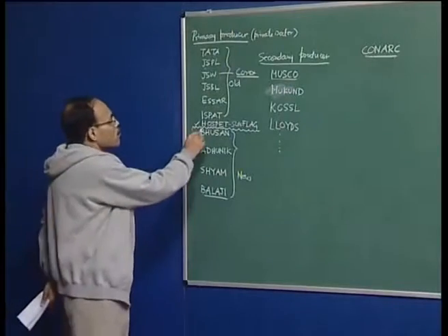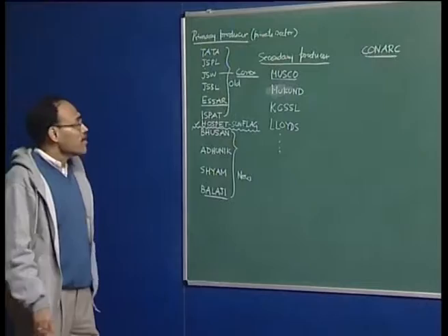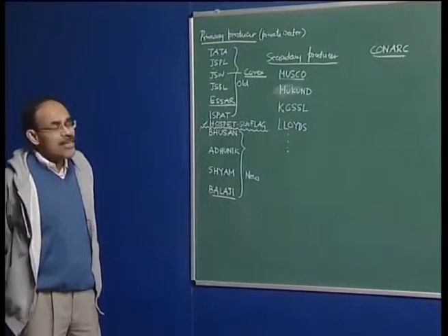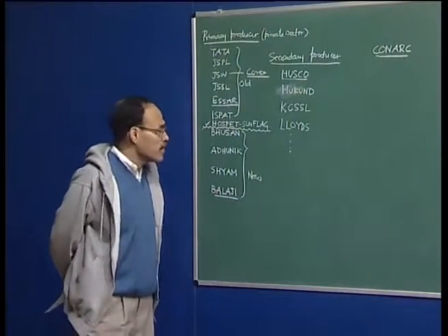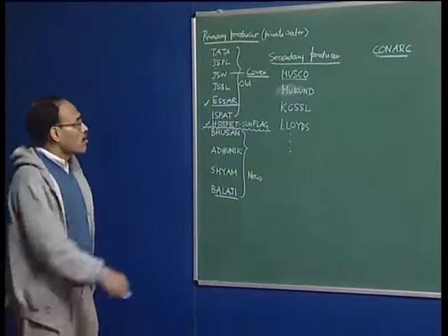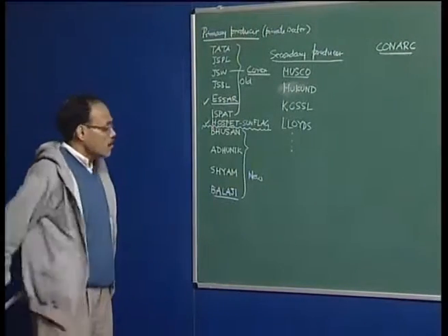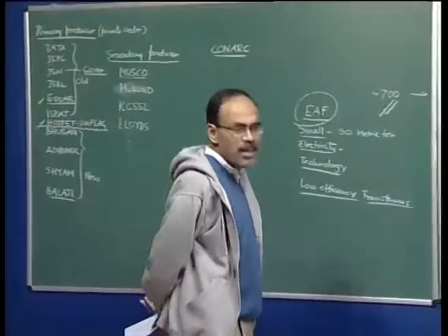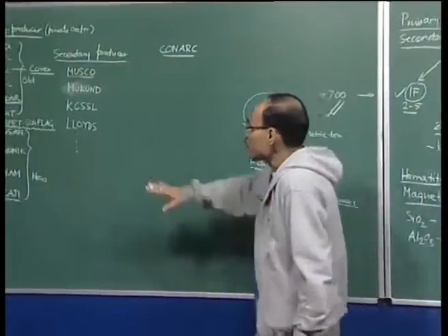So if you go to SR Steel, you find they have a huge electric furnace facility. By the way, SR has the biggest DRI plant, 3.6 million tons per annum. That is their rated capacity of the DRI facility with the SR group. So they make briquettes and they charge it into the electric arc furnace. They have a little bit bigger size electric arc furnace, I think more than 100-ton size, and there they produce the steel. So it's not the same.